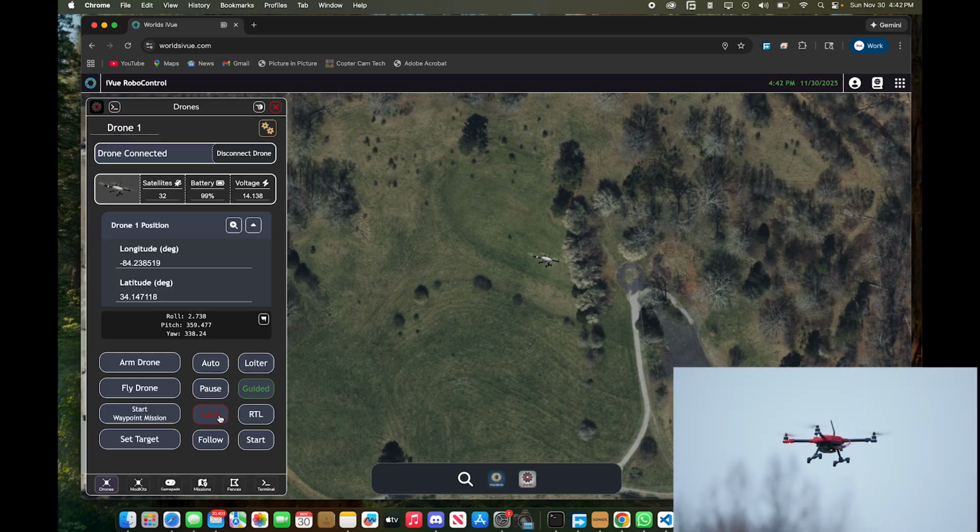And the rotation is back, so it doesn't look like it's an ESC problem, which is kind of good, but on the other hand, what the hell is it? So it's almost got to be an MLRS radio problem, but I don't know. Gosh darned it all.